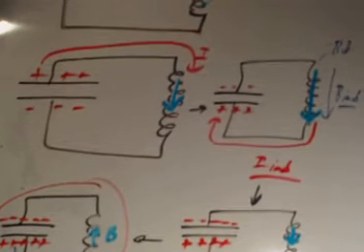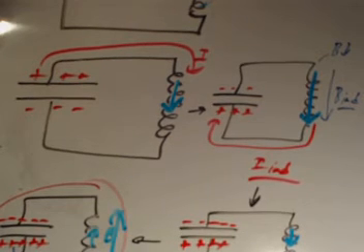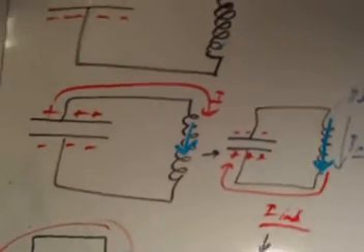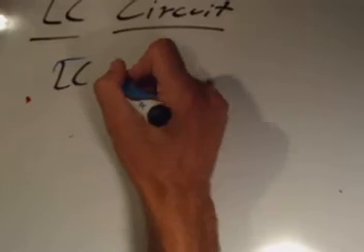And so what will eventually happen is the capacitor will become fully discharged. The inductor will be left with a huge magnetic field in it like that, and the cycle will just start to repeat itself. So what this whole cycle is here, the fact that the charge on the capacitor constantly sloshes back and forth between this polarity and that polarity, and this polarity and that polarity, what you've made here is an oscillator like that. So the system here is called an LC oscillator.